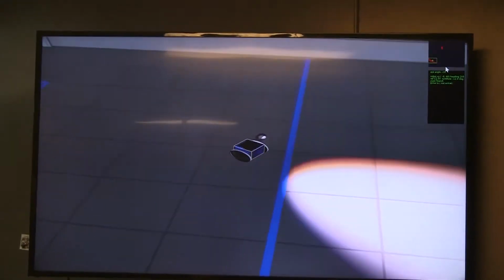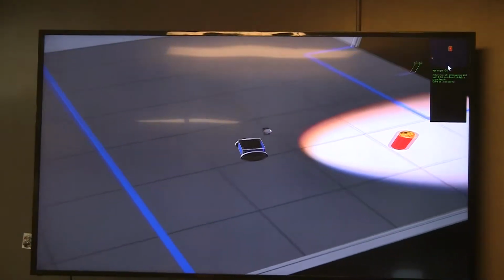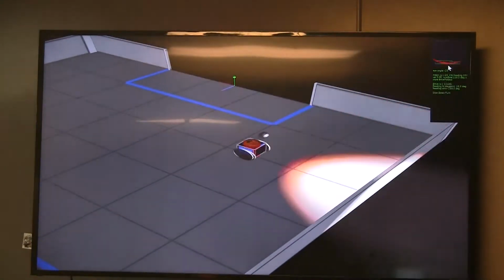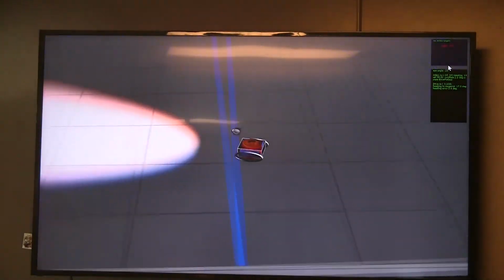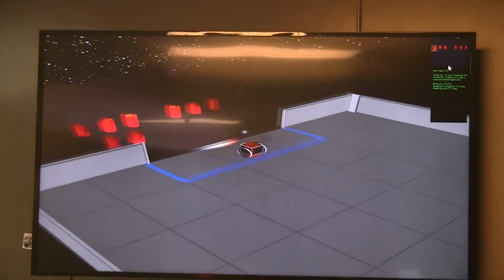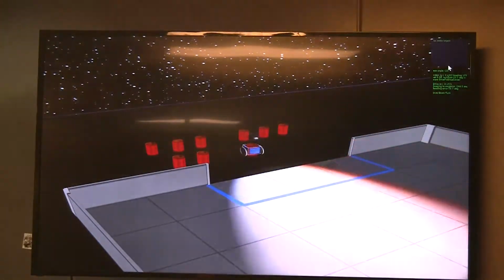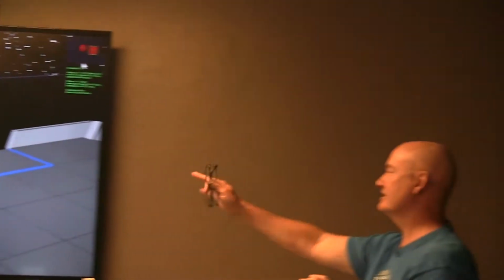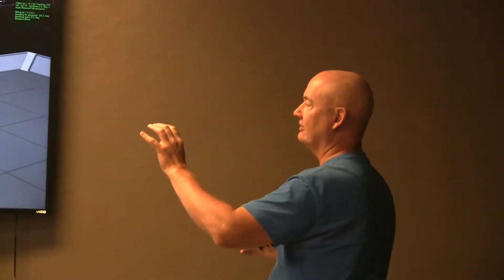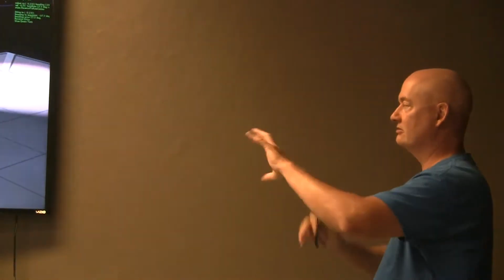With my real robot, which is stepper motor based, I think one of the things that allowed it to not have such large errors in odometry was that I would execute a limited number of turns. Whereas in this case, as I'm acquiring a target, I'm making corrections on the fly to the rotational rate of the robot.